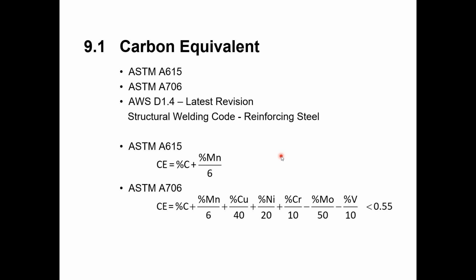Basically, what the welding code is saying there is, don't set up your welding operation in the middle of Buffalo, New York, out underneath a covered roof with no walls, so that in the wintertime you're out there trying to weld, and the ambient temperature is so low that even if preheat isn't required for the bar, it's going to cause rapid cooling of the bar, which could embrittle the bar just as much as a rapid heating process might.